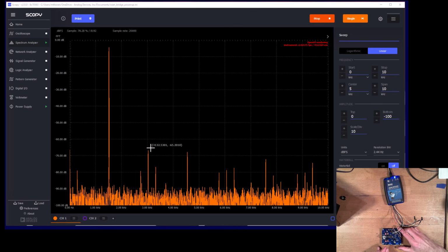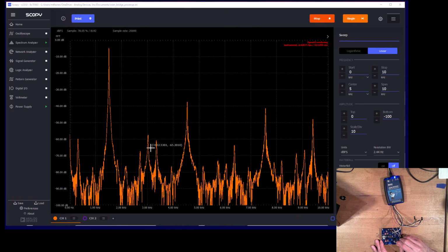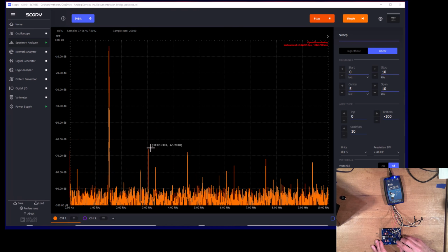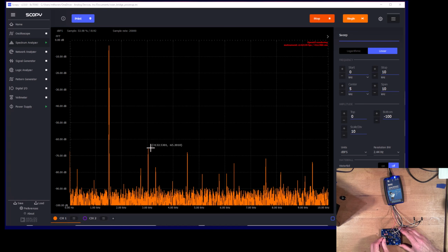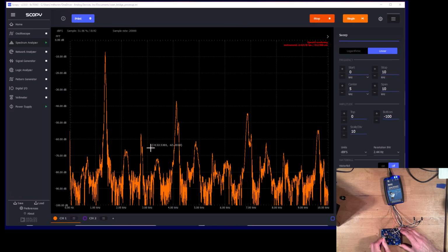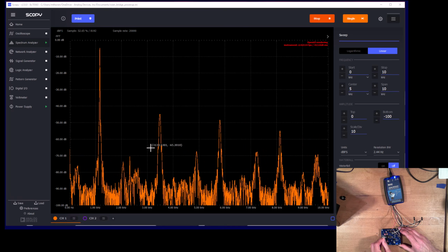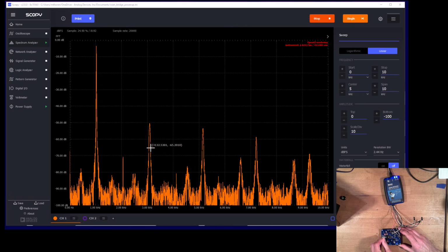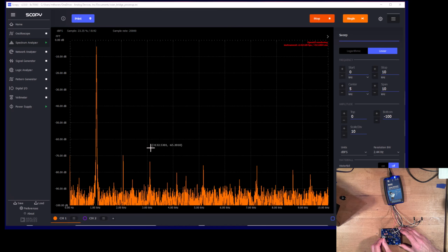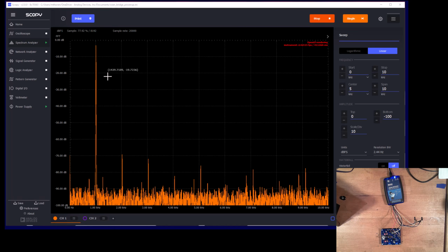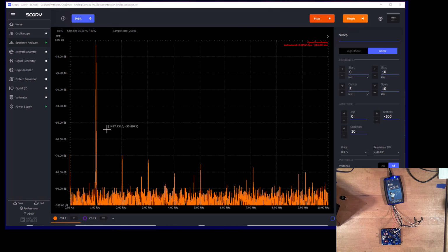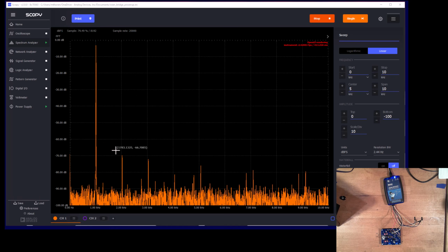Okay, and then let's play around with this a little bit. I'm going to bump the gain a little higher. Yeah, and see, again, it's not that sensitive. And then let's try adjusting the frequency down, back down to a kilohertz. Wow, look at that. Okay, so 10, 20, 30, 40, 50, 60 dB distortion here.